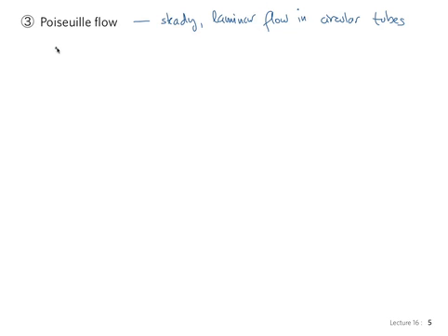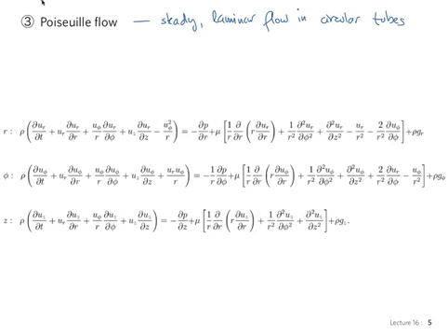So how do we do this? Well, we need to use, as I said, the Navier-Stokes equations in cylindrical coordinates. I'm just going to flash them at you like that, and then I'm going to make them disappear. Basically we write the velocity as a velocity vector, with a component in the z direction, a component in the theta direction, and a component in the radial direction.